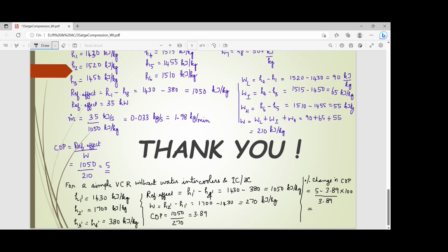Let's look at that. We would have (5 minus 3.89) divided by 3.89, which is 28.53%. So your COP decreases by 28.5% when you avoid using the water intercoolers.